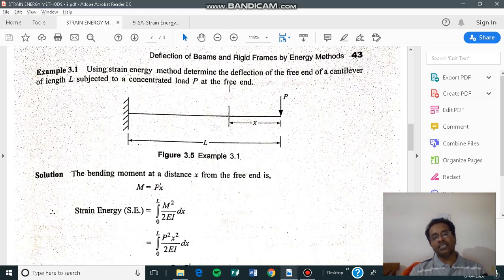Here this minus is not given emphasis because at the end, to calculate the strain energy, this term gets squared. That's why this sign is not taken into account. But if you want, you should take the sign into account, because here it is a single point load. When there are multiple point loads and the directions of loads are of different kinds, which contribute to the sign convention, then we cannot ignore that. Here it is a single load, so ignoring the sign is fine, but when there are multiple loads, ignoring the sign may mislead to an incorrect answer.